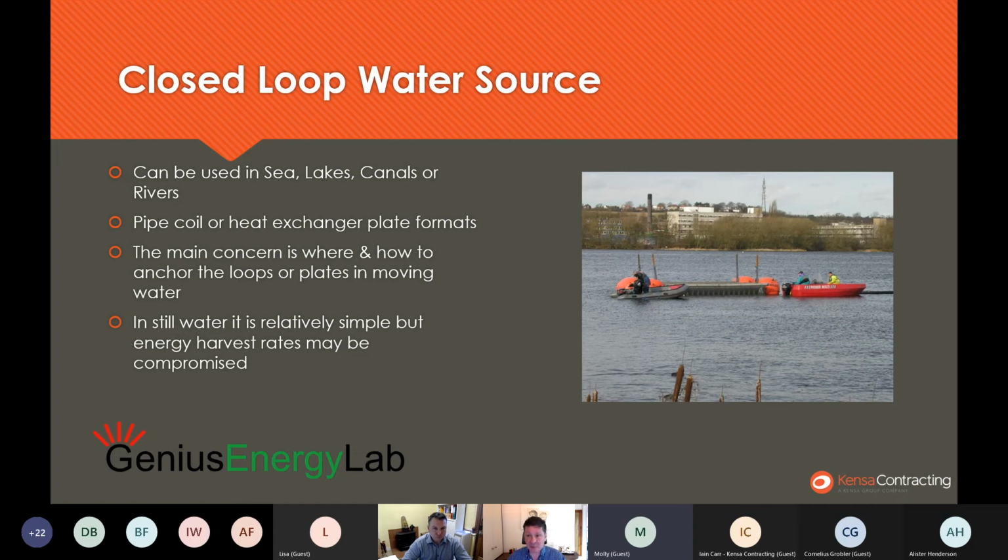In terms of the requirements, it's mainly to do with surface area rather than volume of water. A lot of mainstream consultant engineers will calculate the volume of water, then calculate how much the temperature changes in there and try to work out the capacity of the body of water from that. In actual fact, that misses the main point, which is the energy transfer at the surface, and the solar gains are the main way that it gains heat.